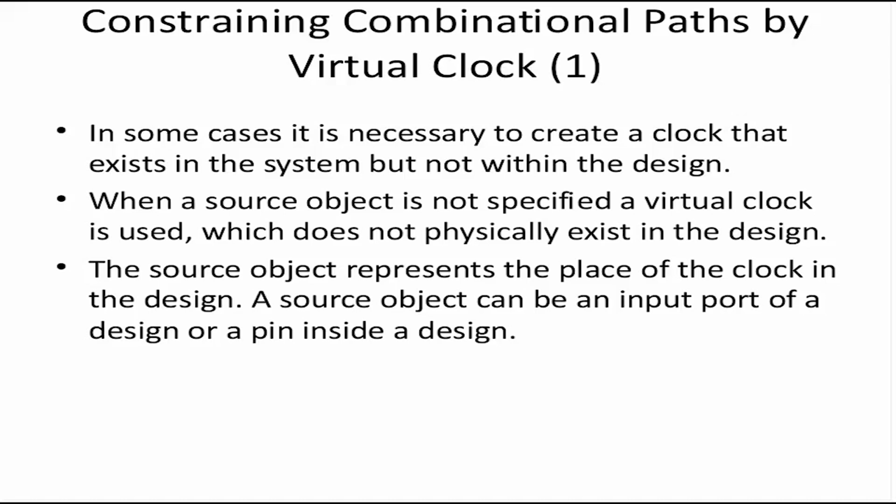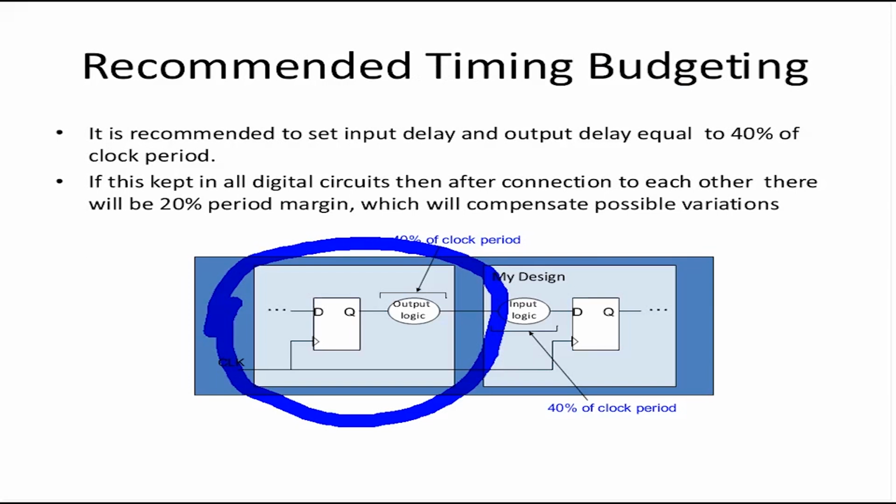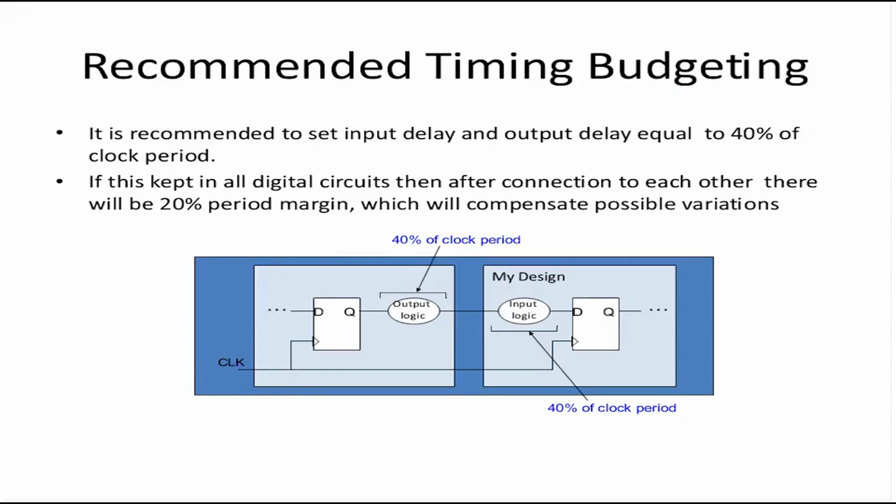So in some cases, it is necessary to create a clock that is not part of the design, but it's part of the system. Let's take this case. My design is the design I am planning to synthesize. This is the clock port.